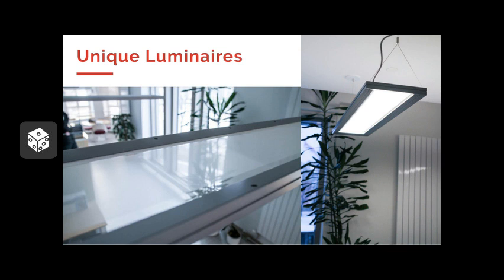These luminaires are really, really unique. The LEDs are actually in the housing, in that metal part around, and they shine through what we call a light guide or a light wave. It's a film that distributes the light evenly, as you can see in the picture on the right. It sends the light up to the ceiling and then down. But when the lights are turned off, you can see through these lights. If you had an overhead daylighting system, it would allow daylight to come through and not have a big, huge metal box preventing the daylight from shining through.